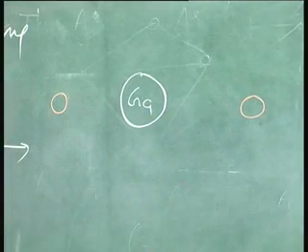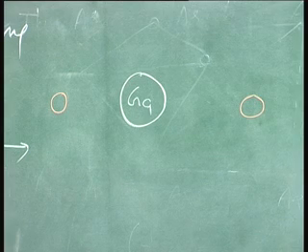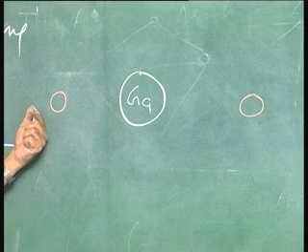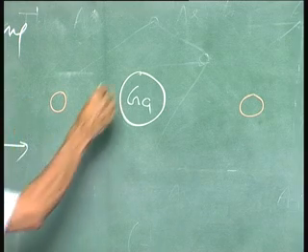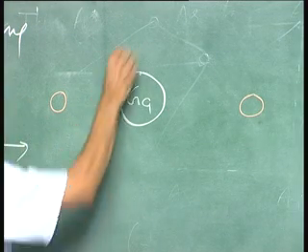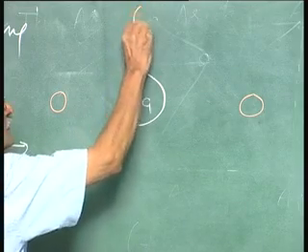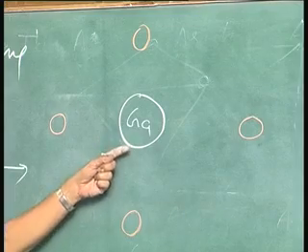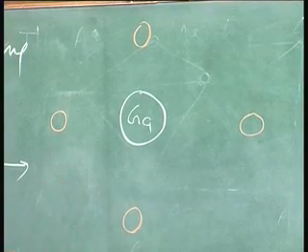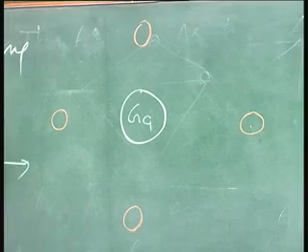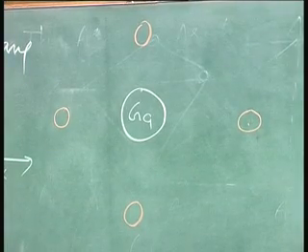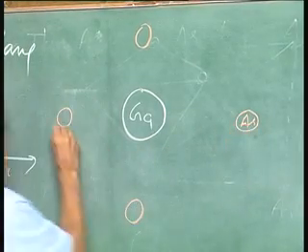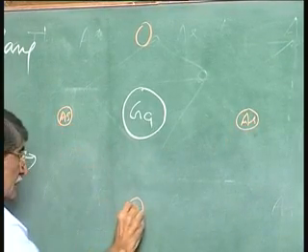I am deliberately putting that small because the tetrahedral radius of gallium is 1.26 angstroms, and this is 1.18 angstroms, smaller. Now, you have got arsenic here. This is 31, that is 33, but the tetrahedral radii of these are different, 1.18 and 1.26. This is arsenic, this is arsenic, this is arsenic.